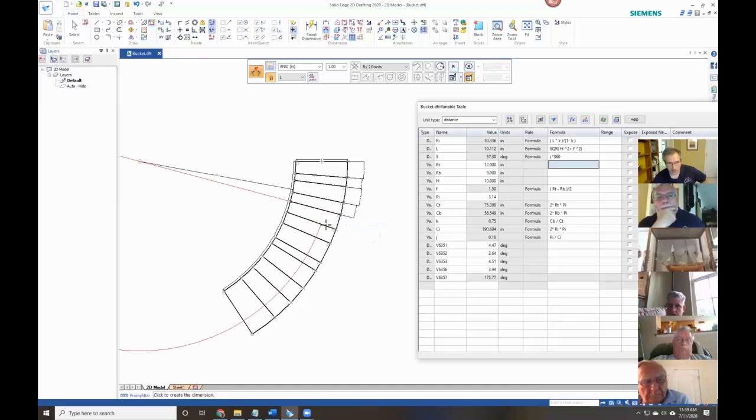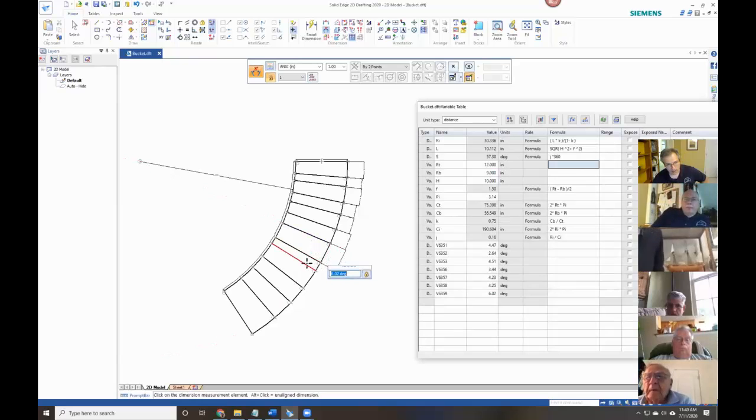So in between each one of these, I'm using the right-click so that I don't start dimensioning from, like if I click here, and then here, and then click here to place the dimension. If I click here without doing the right-click, it's going to be relative to that first one, as you can see. That's why I'm using the right-click to establish a new starting point each time.